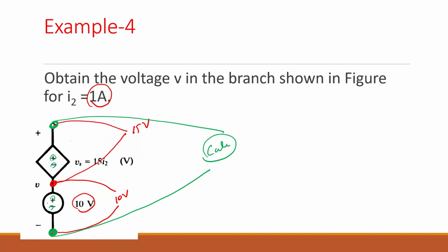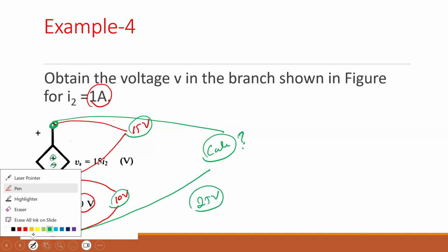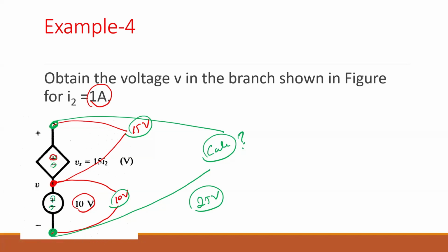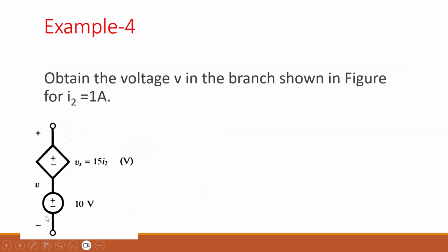But I just wanted to tell you that voltage is always measured between 2 points, and we can have the algebraic sum, and we can find this one if we know the voltages separately. You can't just say yes, it is 25 volts; we always need to look at the signs, the positive and negative sides of these elements, to calculate it properly, and we will learn it later on. Okay, so I think you are now okay with the differences between dependent and independent.